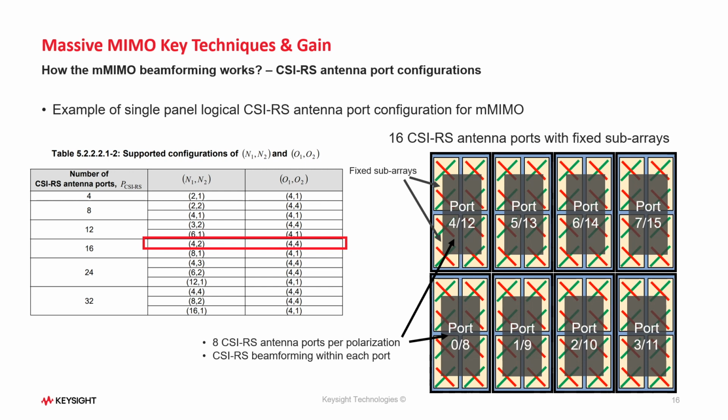In this case, each CSI-RS antenna port consists of 2x2 planar array having the 2-element dual polarized subarrays as the radiating element in the array. And these 2x2 planar arrays can be used for the digital beamforming for CSI-RS beams.